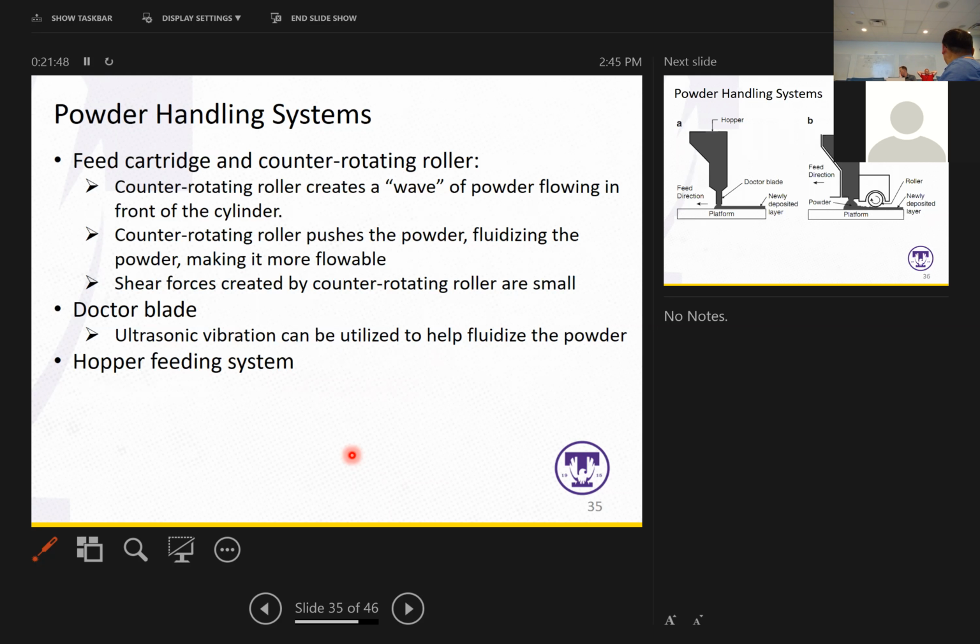Then it's SLS or SLM. That's SLM. Okay. Sure. So the SLM will really give you much better, more uniform properties in Z. Okay. SLS gives you a weird profile, because you can't control where it's going, the spread.